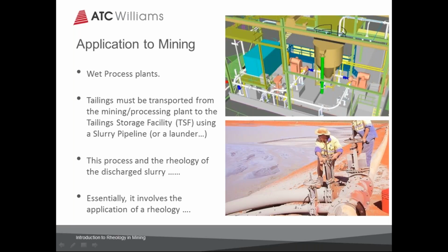Now, where will this be useful in mining? First of all, in any of the flow processes which we have in processing plants, in mixing, mass transfer, all of those sorts of things, those will all be affected by the rheology of the material because that affects how it flows. One of the most interesting applications is when tailings is transported from the processing plant to the storage facility.